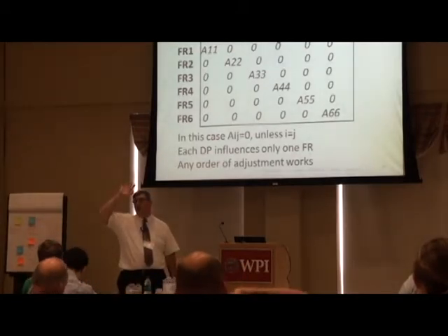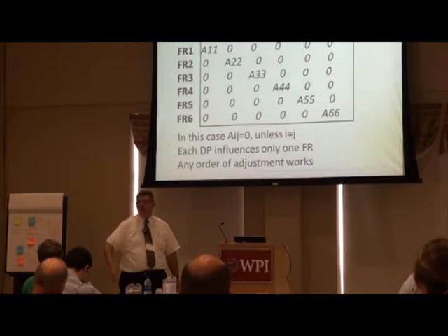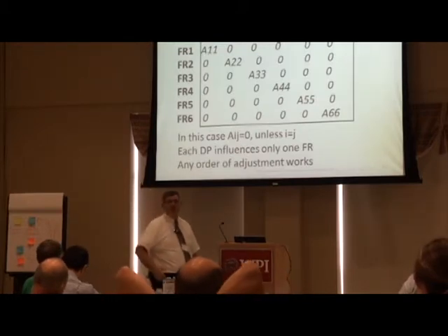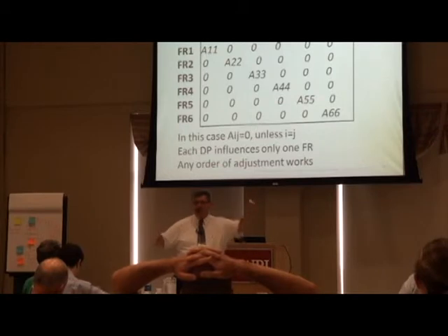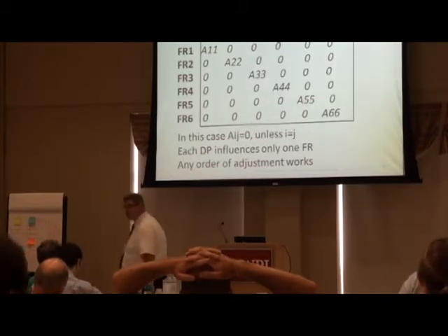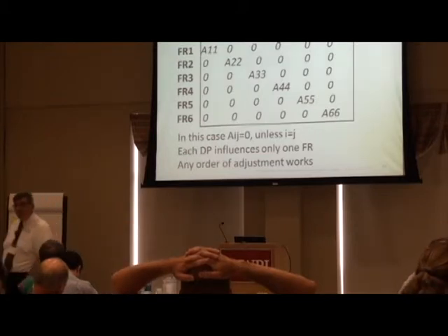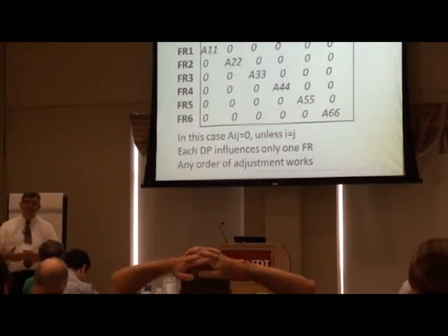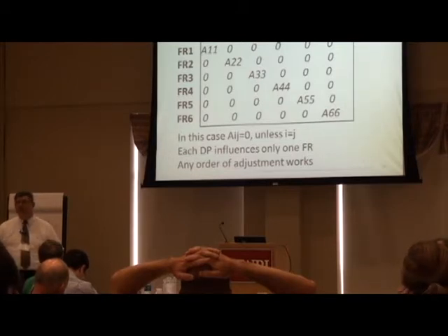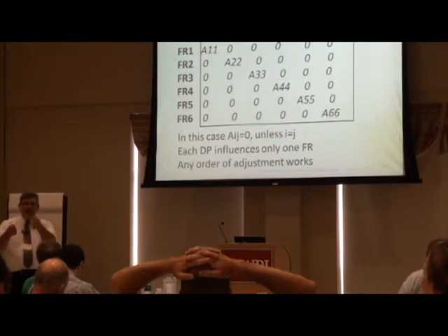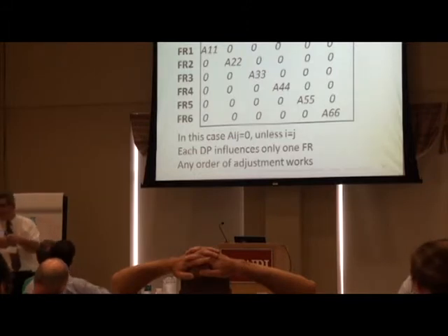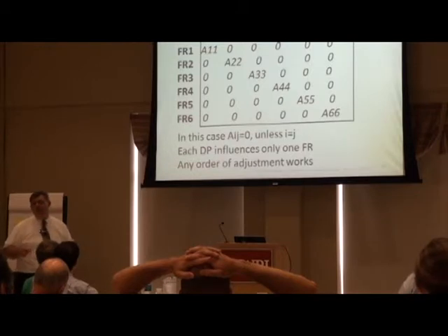And when I look at the matrix, what design parameter is hitting more than one FR that's going to mess me up? So when I change something, I affect something else, like the faucet, or in particular in the medical device field, well, we're going to change the plastic that we're going to make the part from because it's 2 cents cheaper. And then you find out, well, there's something in that actually combines with whatever's inside the device, and now you got a very unhappy patient either because they got sick or the thing melted or whatever happened, right? So it can be very detailed.